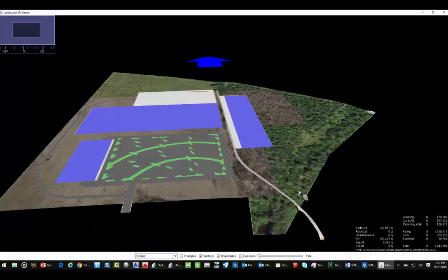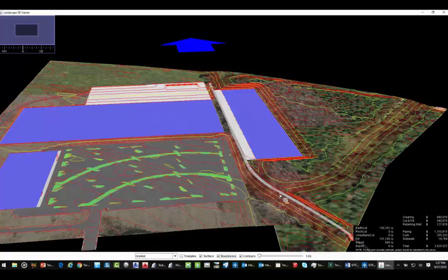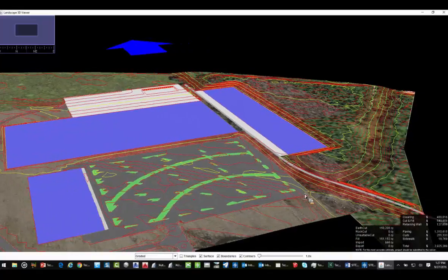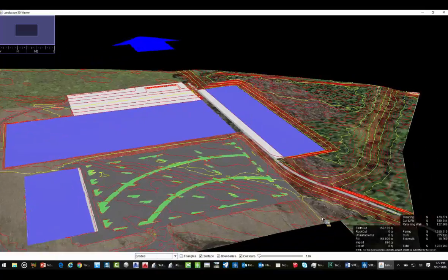It's going to take that and design there. It's going to apply it. Now we're at about 150,000 yards of dirt movement. But it should be, because we're bringing in a rail line, and the rail line can only have so much movement. And once we bring that in, now you're going to see a big difference in my grading. You're going to see a big difference in cost. And again, the client will usually tell you the cost is what it is. What they don't want to do is find out the final cost two, three months from now, four months from now. They want to know what it is today. If it's 2.9 million and we've got to move 150,000 yards of cut and fill, then so be it. That's what it is. We just need to know that.